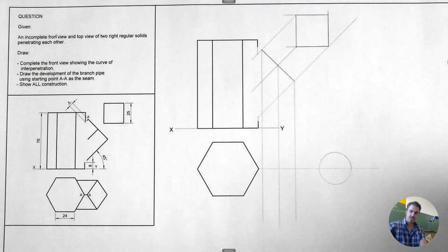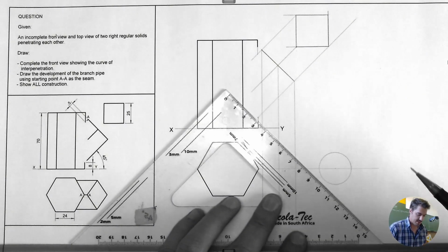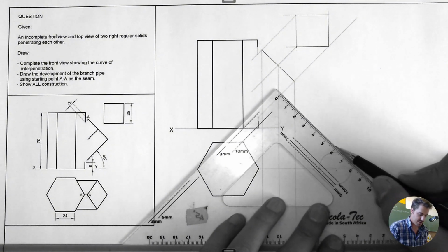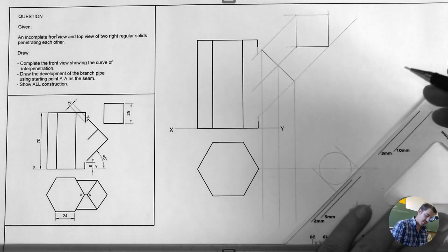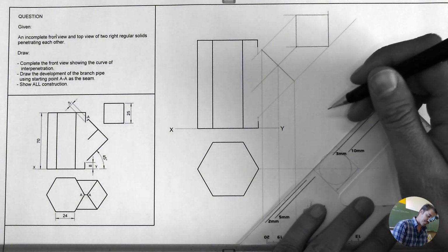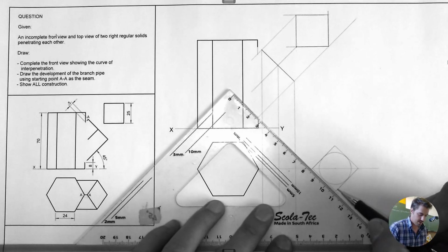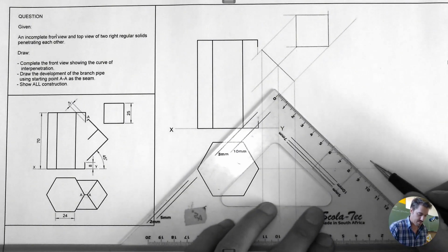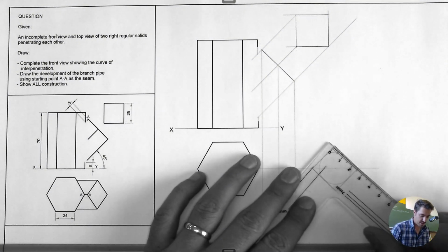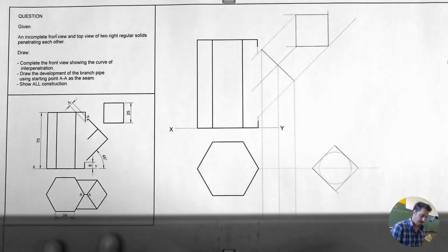Draw in a construction circle, and now we use 45-degree angles on all of the sides, right? So a tangent, you draw a tangent here, tangent on the side here. Make sure it touches, it has to touch on the circle in order to be a tangent. Alright, so now you should have a square that has a base of 25, and we can double check this if we want, measure that and see, yes, that's exactly what we want. Now we can project these points in.